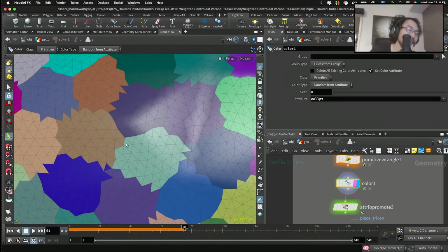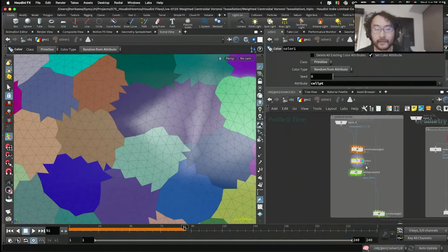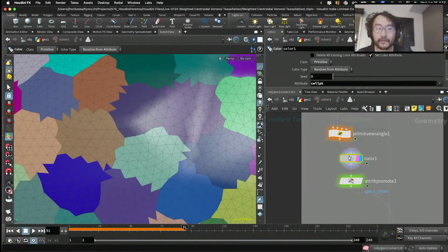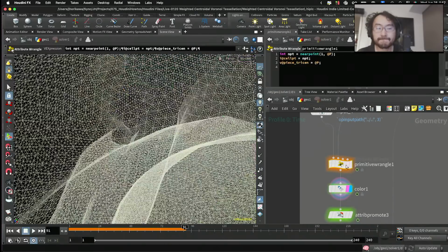triangles, and you can calculate the centroid for each triangle just by getting at P, and you can multiply weight to each of the centroid and then add all these weighted point position and then divide it by the total amount of weight, and that will give you the result, I guess. Yeah, that's the way to go, I guess. That should do it.